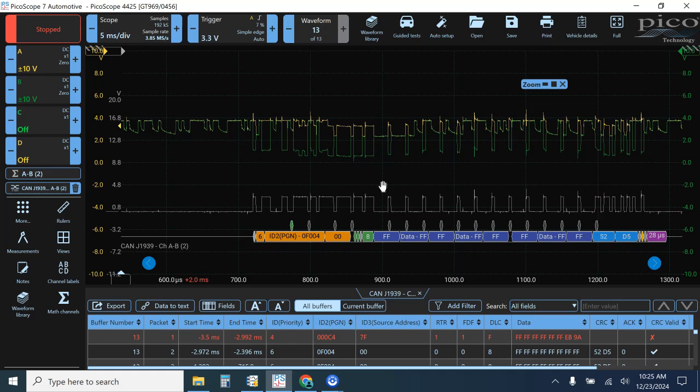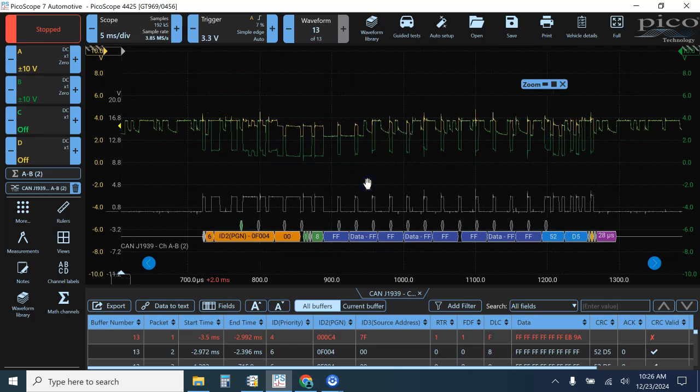We have occasional error frames on the CAN bus, and maybe one or more devices that are not communicating. I may have DTCs for that device, since its message is not being present. We can definitely tell that we've got something electrically wrong with this CAN bus.